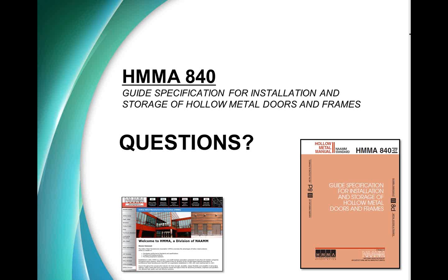Depending on manufacturer, their recommendation, and the job construction, assuming that's all as recommended, the knockdown drywall frame should be installed within like 15 minutes, really. They're very easy to install if everything is correct, and it's very workable and easy to adjust. Now, the key to that is it's got to go into either a wood stud or a steel stud wall.